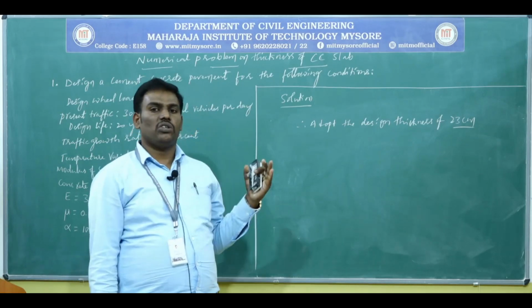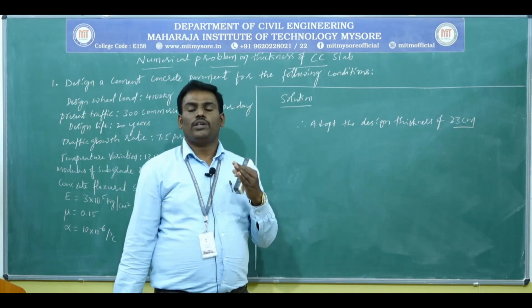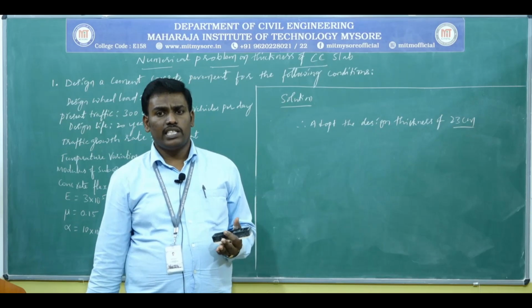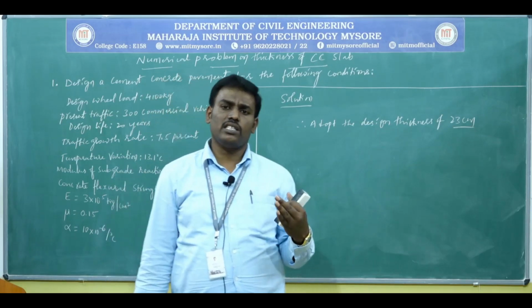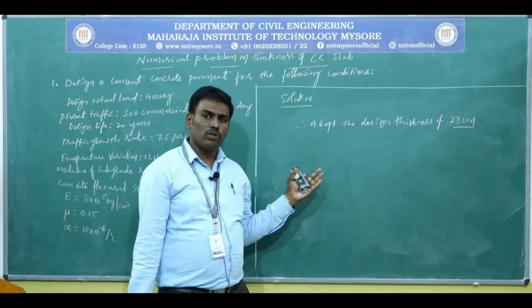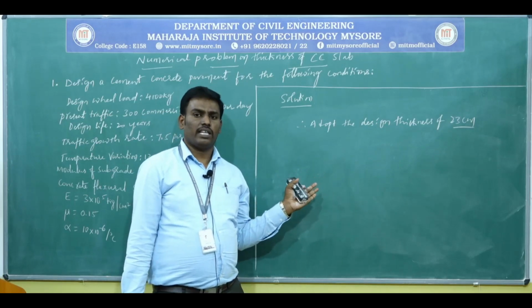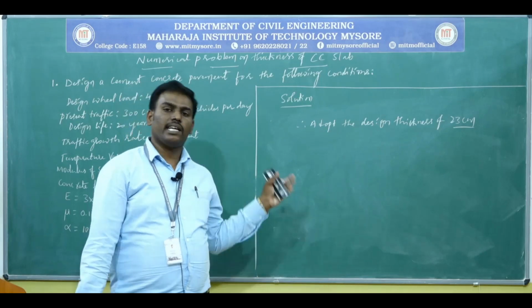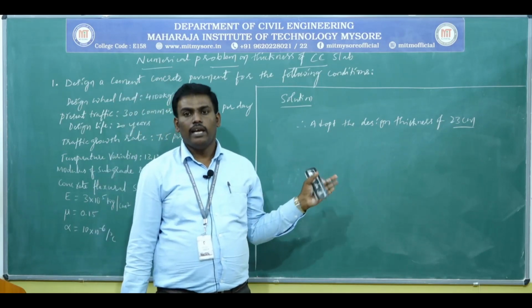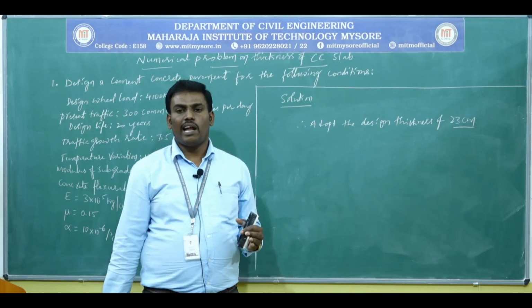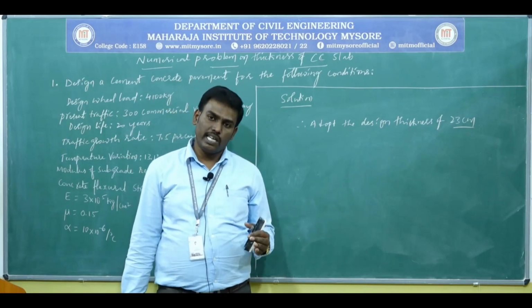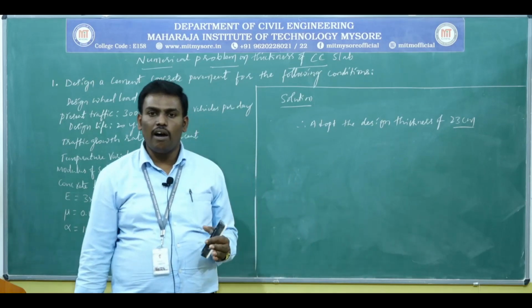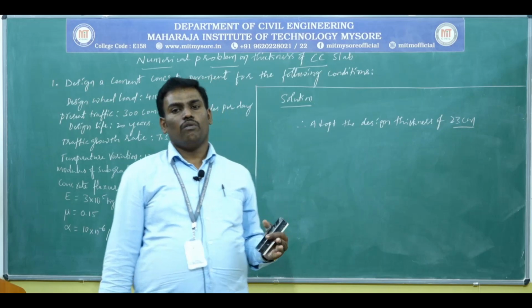Once you find the residual strength of concrete, you need to find the wheel load stress at the edge region, by using the IRC 58/2002 stress chart for the respective k value and the respective thickness. Then you need to check the available factor of safety on the load stress, which is the ratio of residual strength of concrete to the wheel load stress.